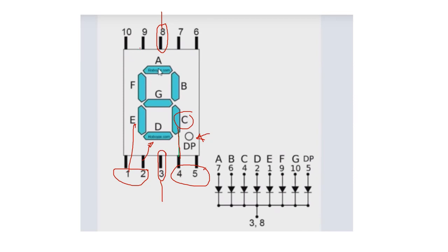Then F, you come back up here. Pin 10 lights G, because it has to go in there to pick the G. Then 9 is coming here, and 8 is already connected to the cathode, and 7 is on A. Then 8 and 6 connect pin B. So that is how those pins are responsible for lighting those particular elements.